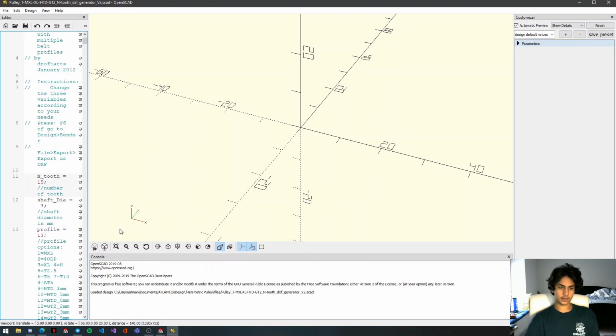Okay, so now we're going to set this tooth count to, let's go, 40 teeth. The gear ratio for this drivetrain is going to be 16.1 to 1. I think that 20 to 1 is a good ratio, but for this year, I think we're going a bit faster, so 16 to 1. Yeah, so we're going to set this to 40 teeth, and then we'll make another pulley that's 34 teeth.